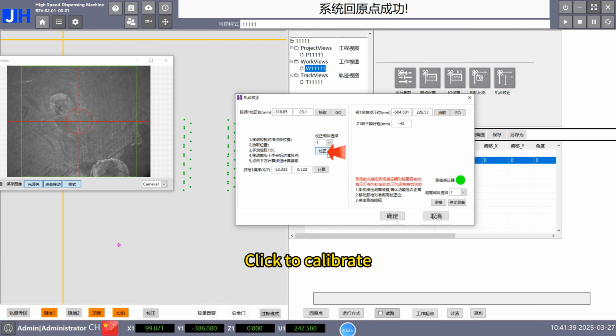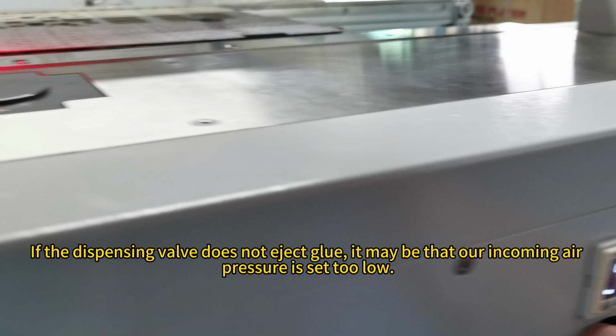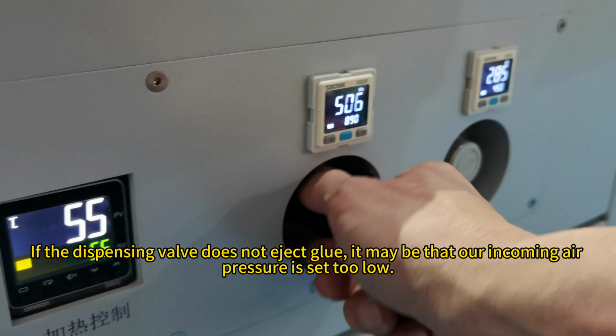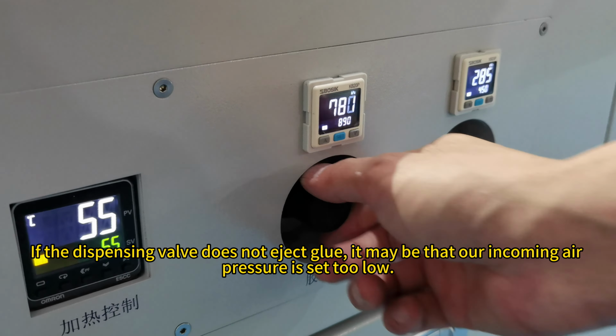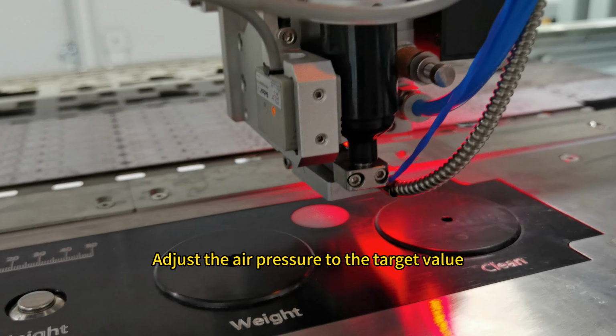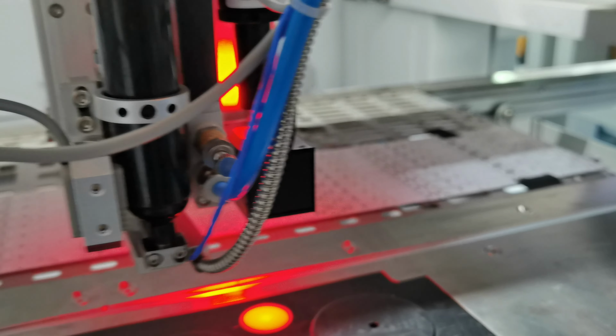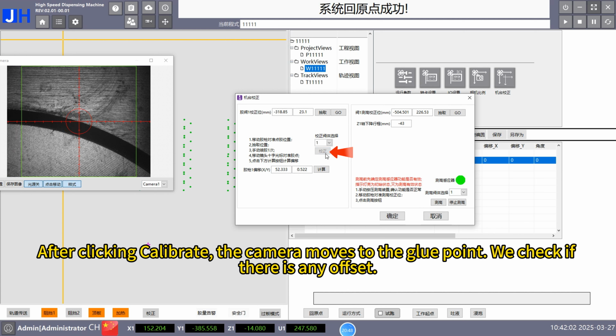Click to calibrate. If the dispensing valve does not eject glue, it may be that our incoming air pressure is set too low. Adjust the air pressure to the target value. After clicking Calibrate, the camera moves to the glue point. We check if there is any offset.